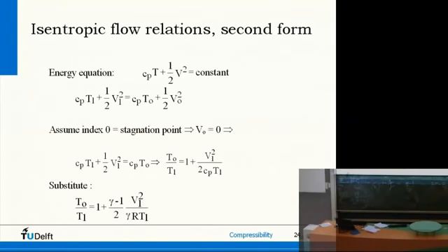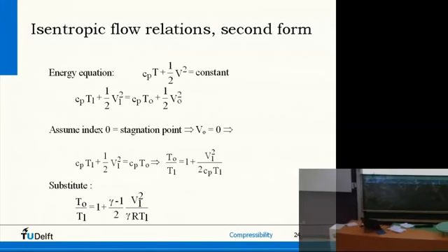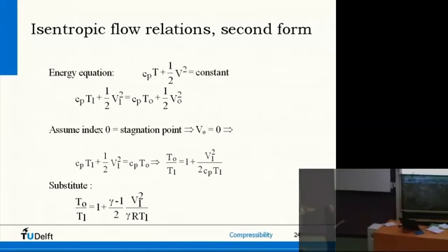So this Cp here, I'm going to replace by gamma R divided by gamma minus 1. But of course I have to divide over it, so the gamma R turns up here, gamma minus 1 there. So reworking this specific heat coefficient, I get to this version. And now see, here's my a squared, right? My a1 squared. So I have V1 squared over a1 squared, so Mach number squared.